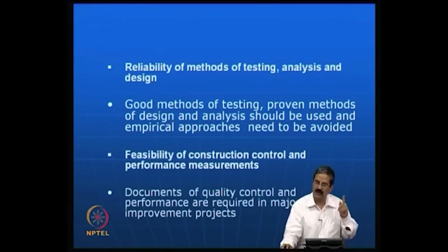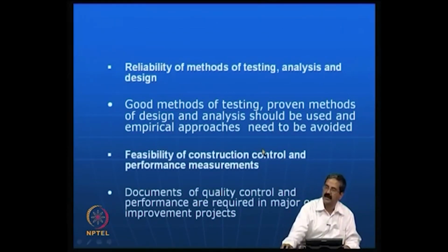Even the choice of ground improvement techniques depends on this, because I have seen a case wherein the soil's grain size distribution itself can be misleading. Based on the grain size distributions also, there is a very thin margin in choosing these materials. The efficiency of the technique depends on many of these properties of the soils that need to be improved. So, one should do proper testing.